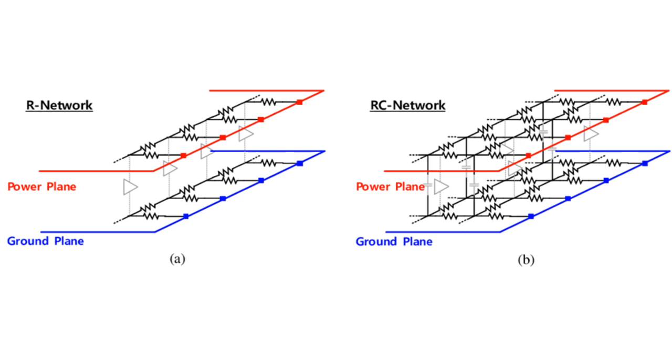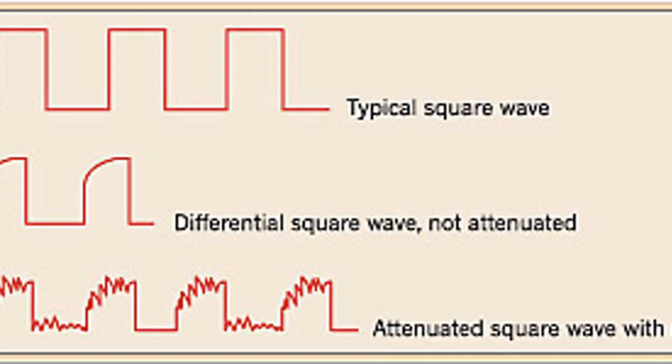Power and ground paths have very low, but finite non-zero impedances. Ground loops need to be kept low. Signal degradation due to EMI. EMI increases with frequency and faster signal rise times. Radiation far field strength increases with frequency linearly for single-ended signal currents, and as the square for differential signal currents.